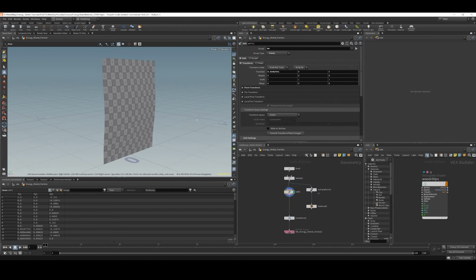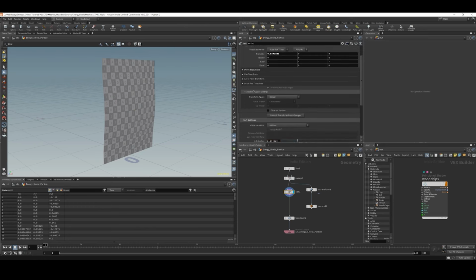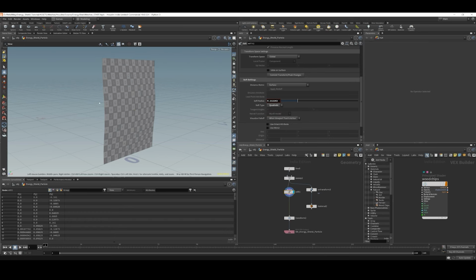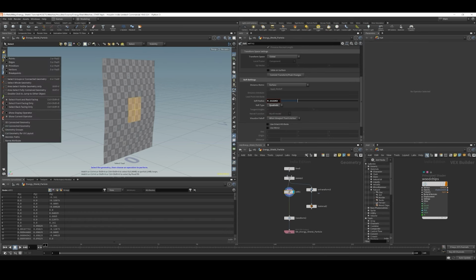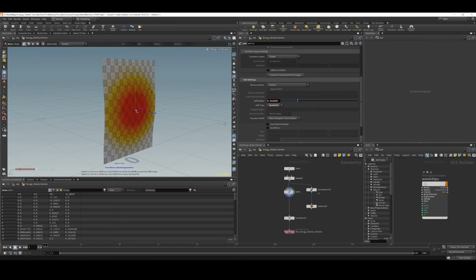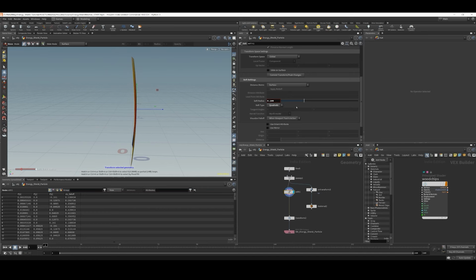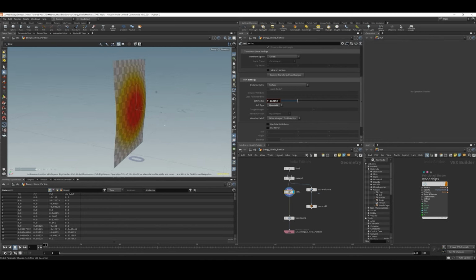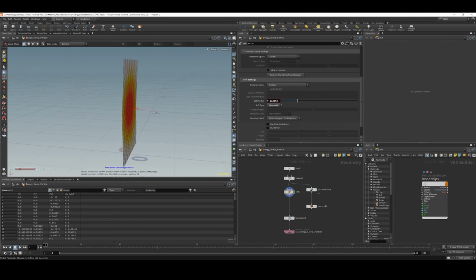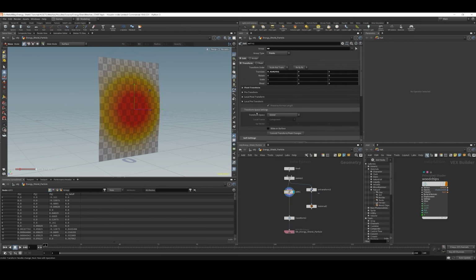And what's great about this edit node, I added this. I didn't just start editing the points. I dropped it down so that I could go to this soft setting. And what I'm doing is I'm making sure points are active. I select my point, and this soft setting gives me a value that allows me to translate all the vertices attached. You could pull it out further, but I am kind of giving it this kind of edge with just a bump out in the middle. So as you pull out your vertices, you can see that it's only going to affect the area with that kind of falloff radius on it. So that's a great part of that edit node that I really like.